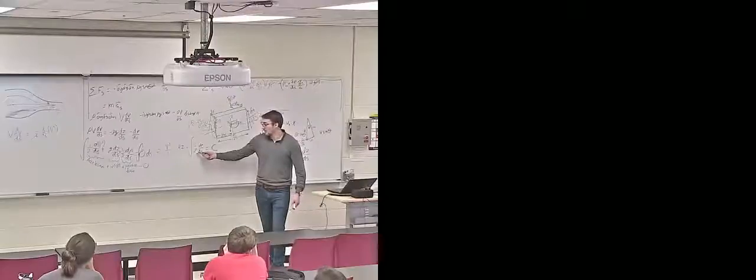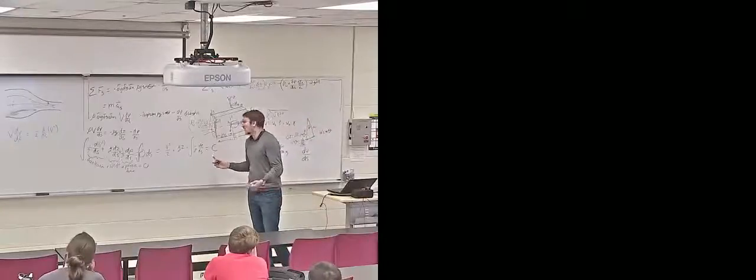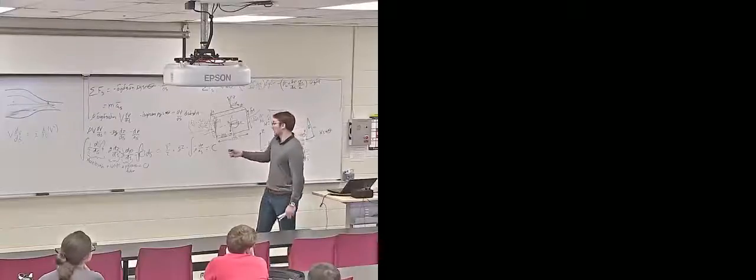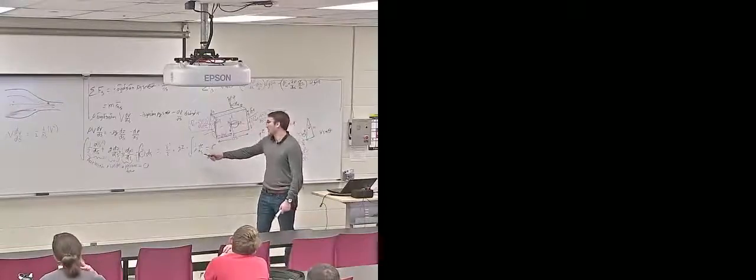Well, we haven't made any assumptions yet. None of the assumptions that were made, that is, streamlines, steady flow, inviscid. Was there anything in there about incompressibility? No. So we can't make any assumptions yet about how rho or pressure vary along the streamline. An example of how we could assume is we could say it follows the ideal gas law, and here's the pressure along the streamline, so you can calculate how rho varies. But in general, you can't integrate this if you don't know how p as a function of s changes, or how rho as a function of s changes.